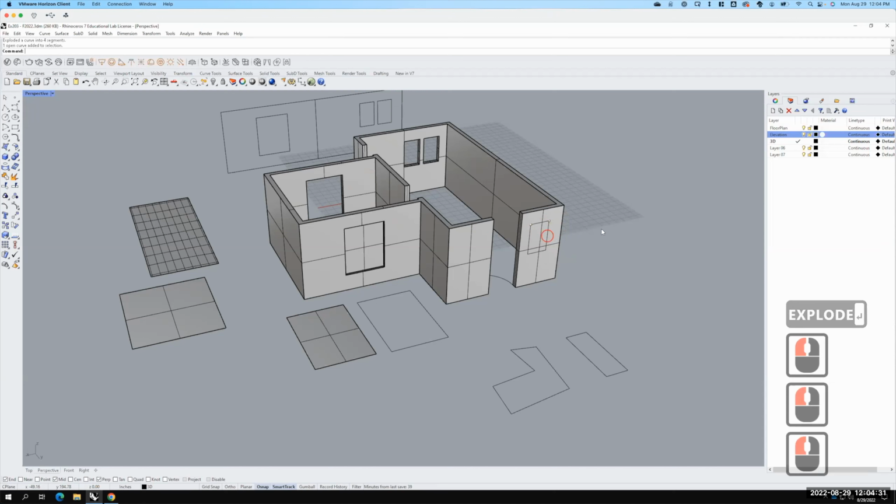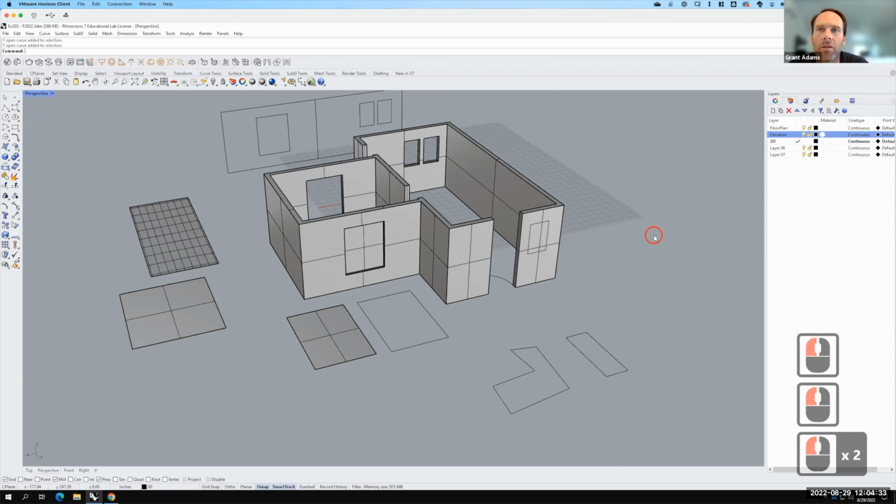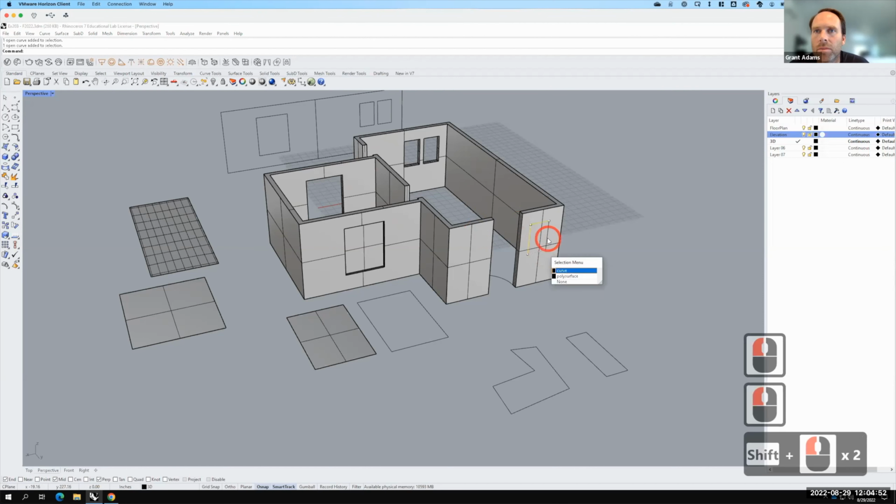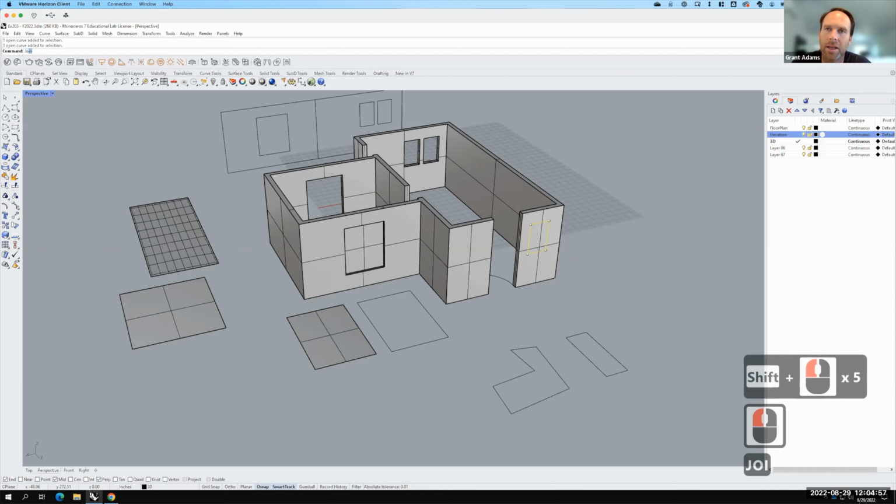They're separate, etc. When you get to the make curve or the make hole part right here, it's going to ask for a planar closed curve, and you don't have one here, so it won't let you select it. So I would have to join these four together in order to use the make hole. I'd have to go back and join them. So I'd select them and then type join. Now I could do the make hole.